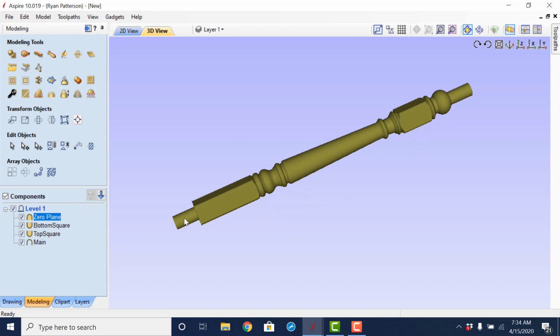So now that we have our zero plane with some thickness, that is not going to allow our cutter to come all the way down to the center of our turning. We could change the size of that plane anytime we want. If we think that we could make this tab a little smaller in diameter, we could do that as long as we think it's going to hold in place.